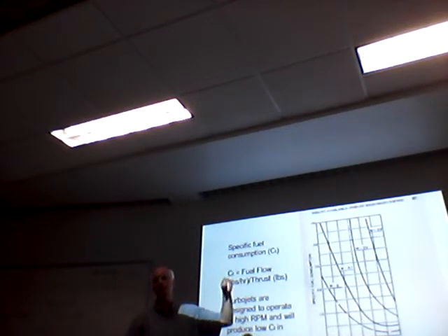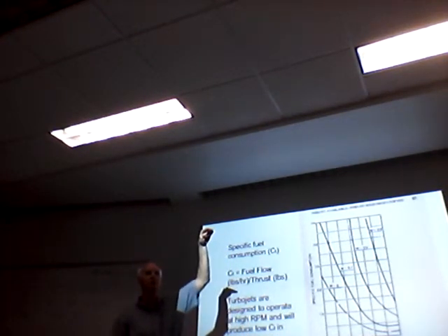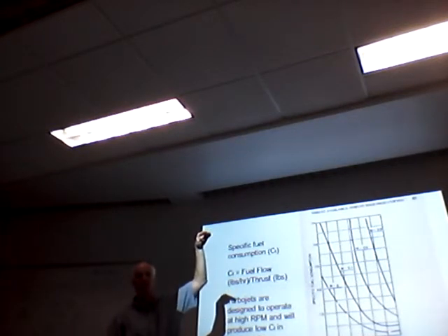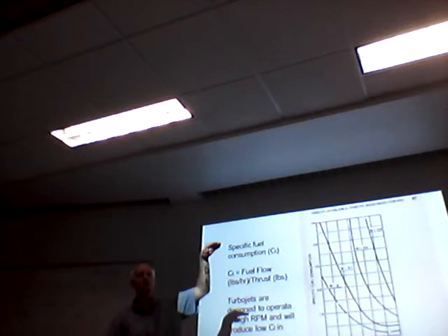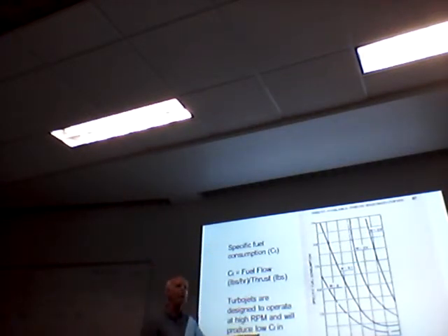So when the temperature basically stays the same from that point on, now you get decreased air density, but no decreased air temperature. So it doesn't help. So all the way up, it's more efficient, effectively, the higher they go, but also at high RPM. And that's the counterintuitive part. So you get the best specific fuel consumption, the most efficient use of your fuel, at high RPM as opposed to low RPM in a jet engine. So high RPM, high altitude to a point, okay?